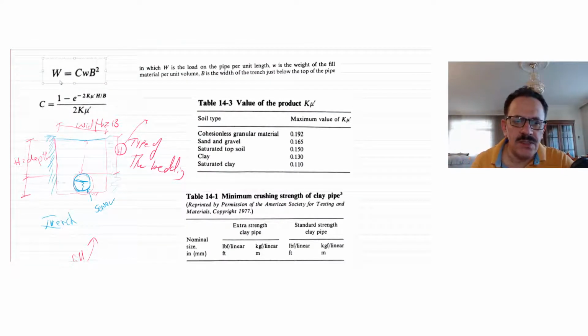Now the question is, do we have a standard bedding? Yes, we have a standard, within the limit that we have. Some of the beddings ask to just lay out the sewer on the bed after excavating. Just put it here on well compacted soil, and carefully fill sand here.